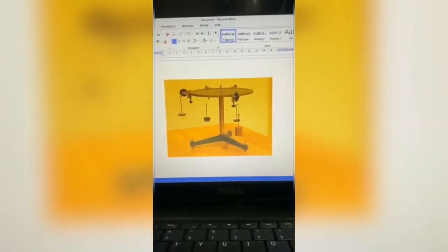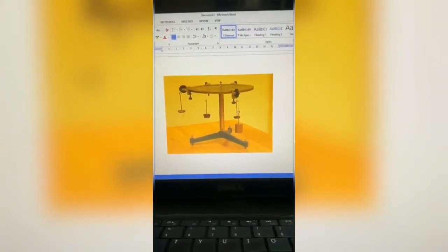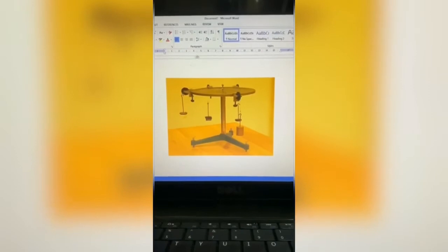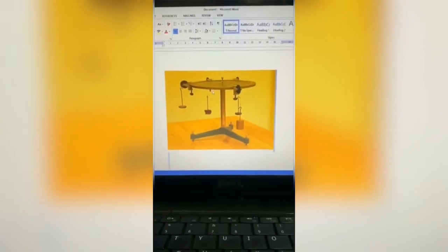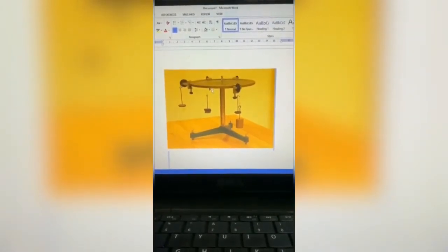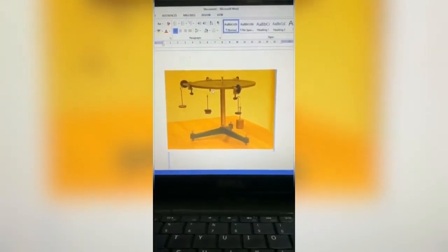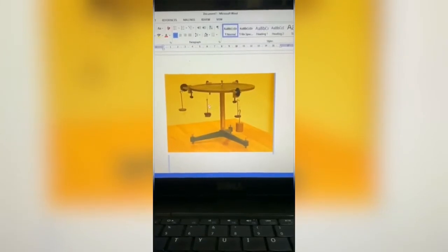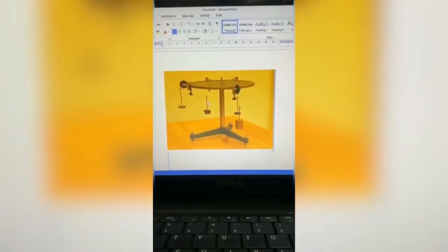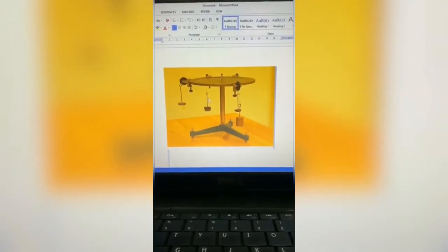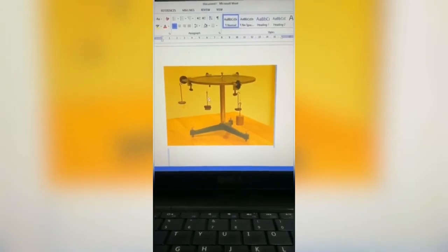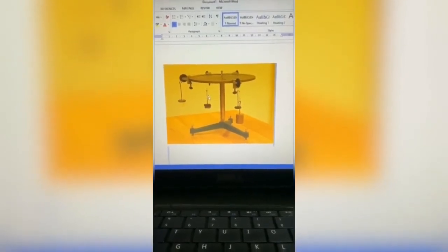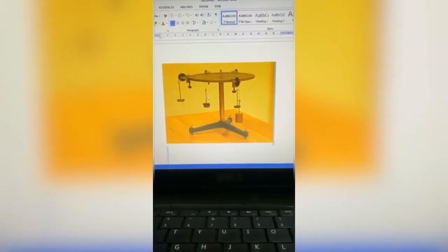First, we set up the apparatus and material as shown in the diagram. Second, hang the right weight for each angle given and mark the direction of force and the force value, referring to the table. Third, record the data in the result table below, and then calculate all the forces acting on the X and Y axes. Fifth, repeat the experiment with the data given in table 2.